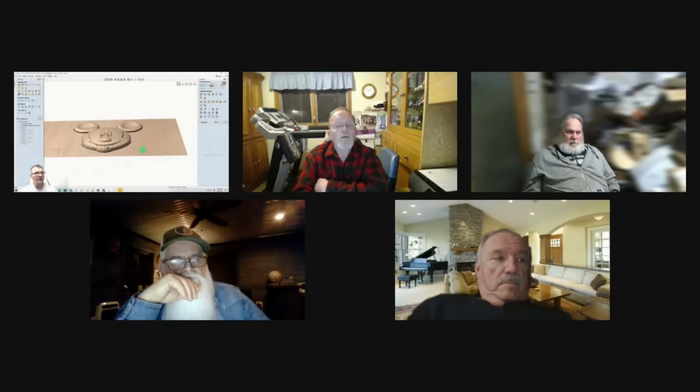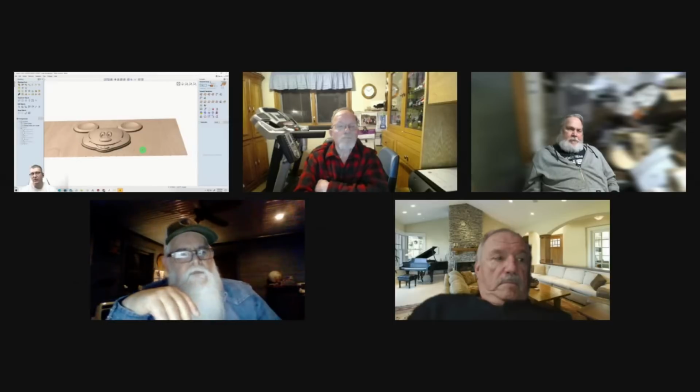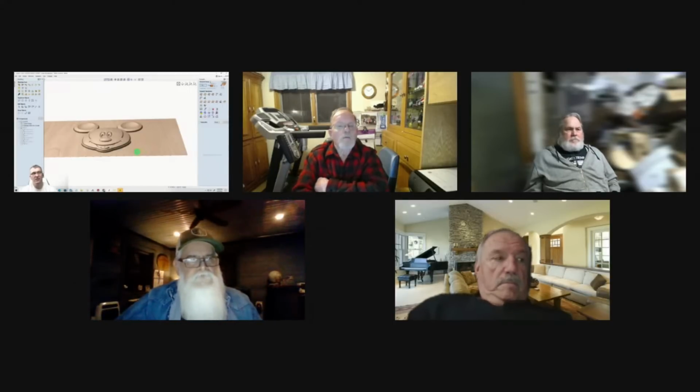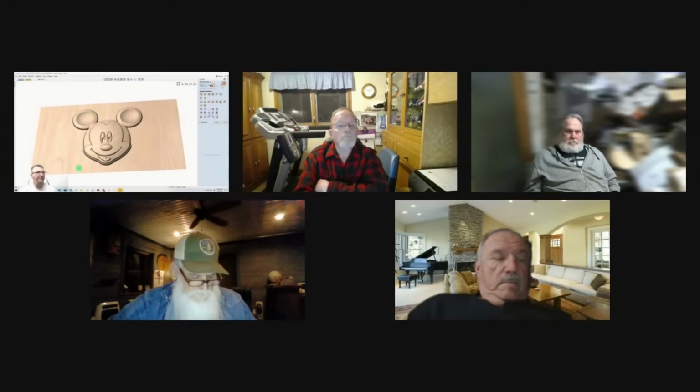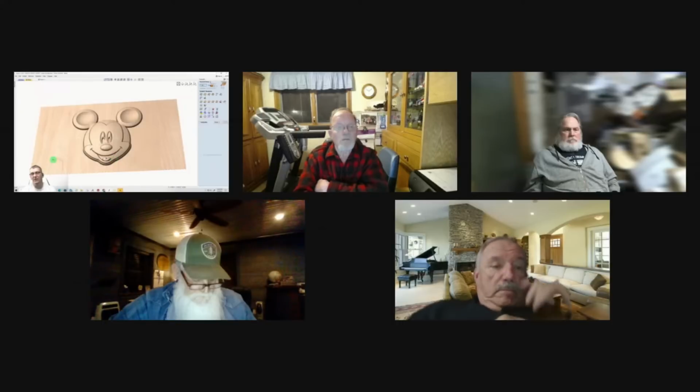Do you recommend setting that up? No, not with this kind of model. With a concave one, like a dish, absolutely. But it's not necessary with this. The reason being, let's say I was carving this and I just want to carve this out because I'm going to cut it out, and I chose to use the model as the boundary. Well, the zero plane is the model, so it's going to consider this whole surface now the model. So I don't want it visible.